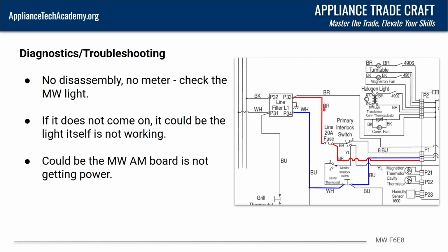Again, voltage potential. You have a voltage potential difference between neutral, which is 0 volts, and line, which is 120 volts. I'm really driving this point home because this is a solid diagnostic tool that's going to help you focus your efforts, and we're going to dive into that a little bit more.